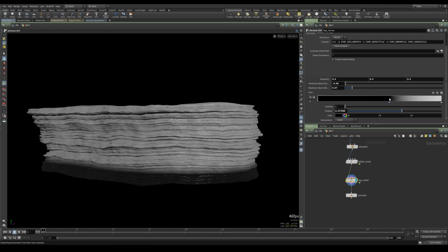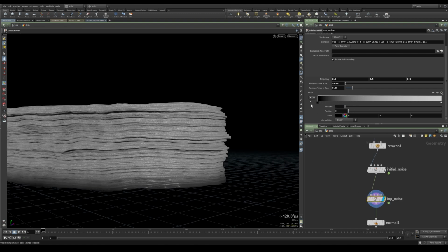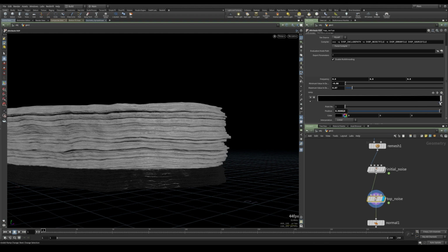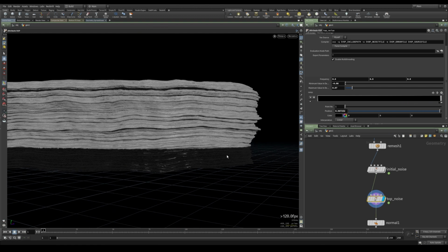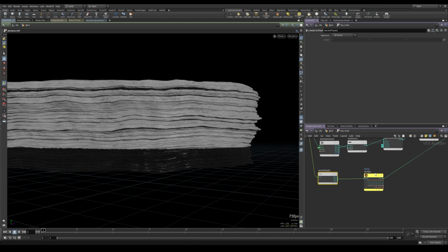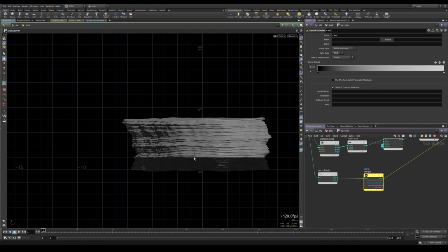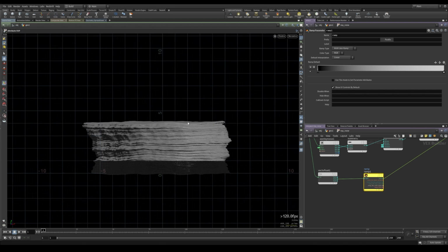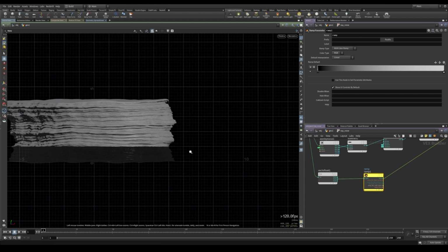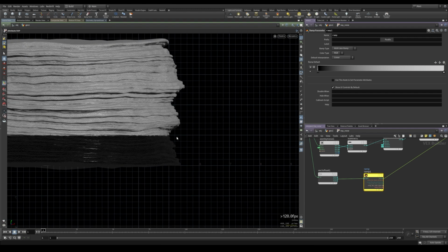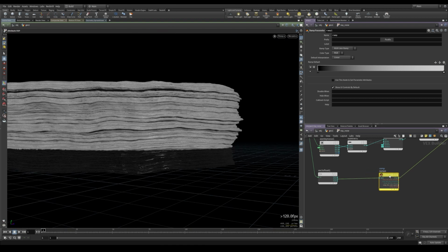Now we are using it for the color, but we are going to use it for a multiply node before the displace along normal. Now the problem is that even if we reach the end of our ramp, we actually aren't even at the middle of our mesh. That's because the ramp does expect values from 0 to 1, as now our rock is 4 point something units tall, and as you can see, the ramp reached only the value 1 at the maximum. So we need to remap this incoming value in a way that our mesh will go from 0 to 1.